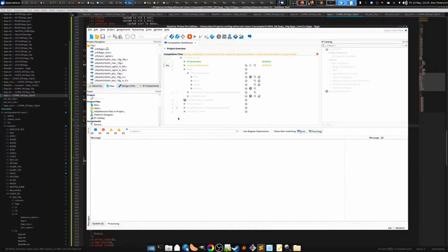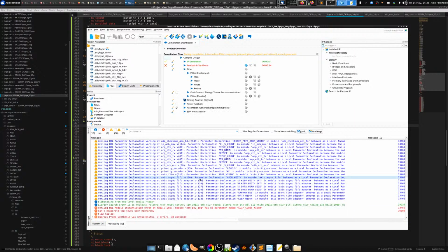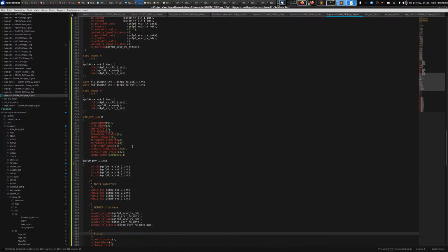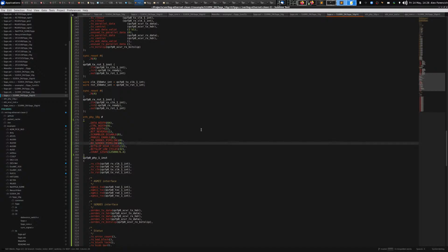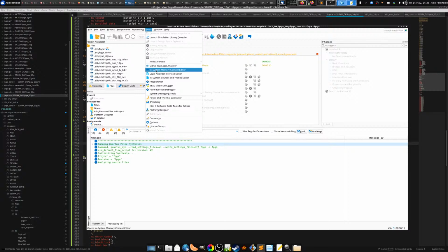Let's try that again. So with Vivado, I think there's maybe a couple different ways you could use the ILAs, but the way I usually use the ILAs is to generate a core for the ILA and then manually instantiate it in the design and make the connections, which works, but it's kind of a pain. Oh, that goes away. All right, third time's the charm, right? Let's let this run here, and I'm going to go ahead and get the logic analyzer stuff running.